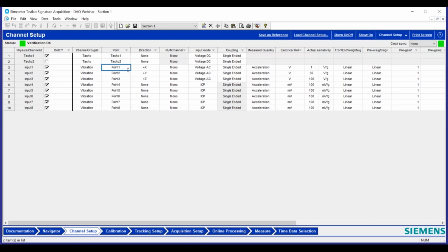And it won't let you have the same name for 2 different channels. Did I see that? Well, you can't have the same. It will warn you. Let's say, for example, we've said channel 1 here. I'll make channel 1. We'll call it 0.1. We'll paste it in the next 2. If I have the same direction, plus X, then I get a warning: duplicate point names found on channels. So that could be very helpful. Confusing to have 2 channels with the exact same name. No, and I noticed it even grays out the measure. It's designed for people like me.